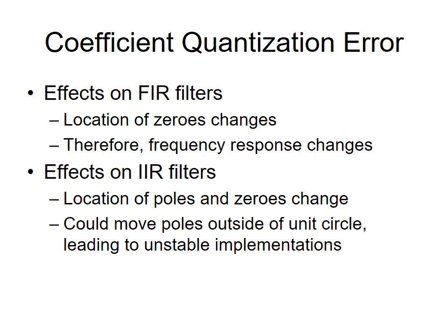Next, effects on IIR filters: the location of poles and zeros will change as in FIR filters, and it could also move poles outside the unit circle, which will lead to an unstable implementation. So the quantization error has effects at the coefficient level, and it should be recognized in both FIR as well as IIR filters.